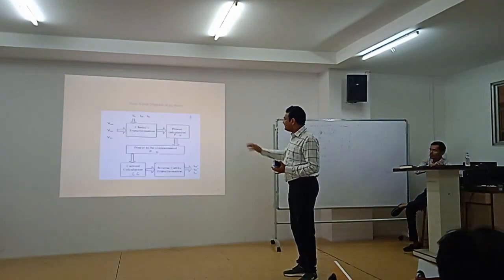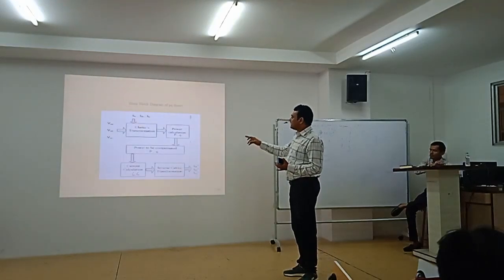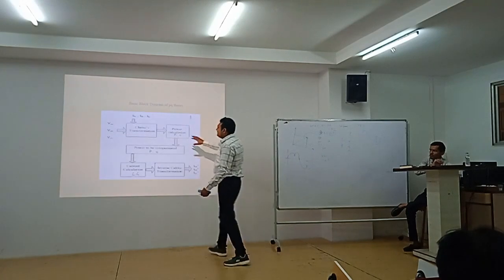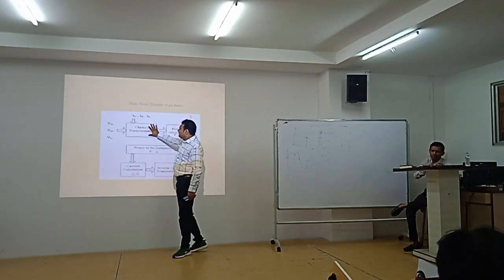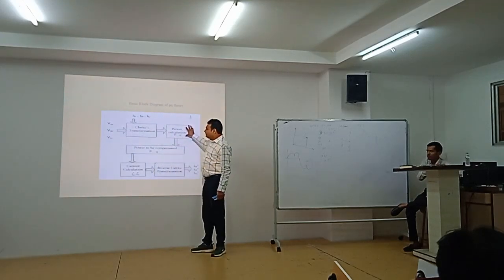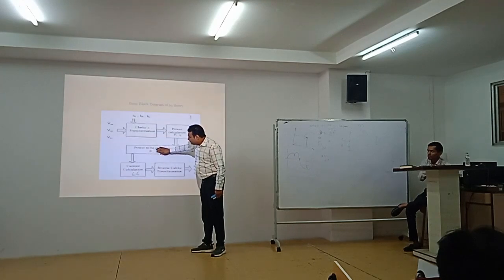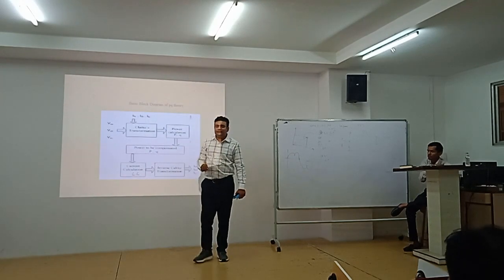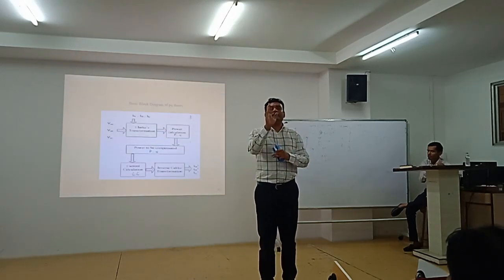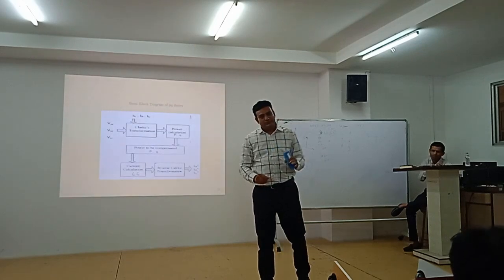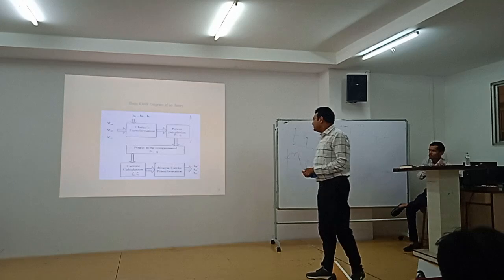I represent generate. This is a basic block diagram. Three signals are taken, three of load current, three of source voltage, then they have developed Clark transformation, yes. Power calculation P and Q, and the power to be compensated is extracted, and from that the reference is generated and injected at 180 degree. So that is the instantaneous reactive power theory.